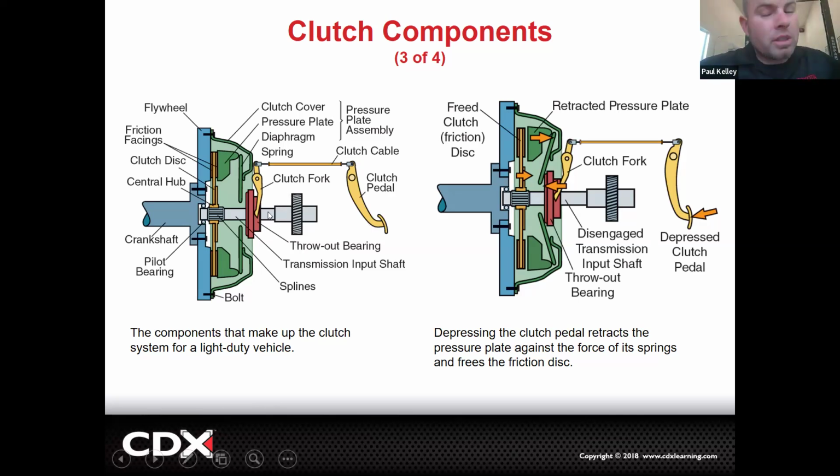I'd be like, all right, I don't think it's a release bearing because it didn't really change sounds with a little movement. But then if you go ahead and throw the pedal in all the way, now this one will stop. And if it's that bearing, the noise will stop, right? So a little, push down all the way, then it's quiet. I'd be thinking my transmission input shaft bearing right there. Kind of makes sense. But if it was the pilot bearing, there'd be no noise. Then you'd throw the pedal all the way down, and then the noise would start. That'd be like a pilot bearing, because remember the speed difference? This one's turning and this one stopped.